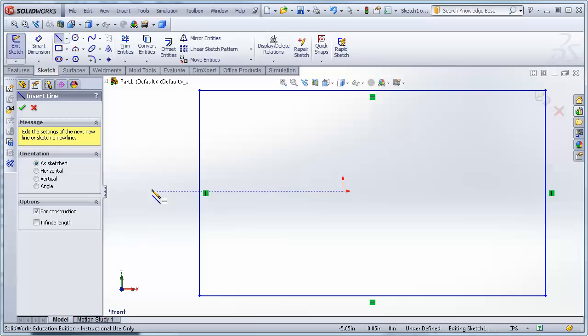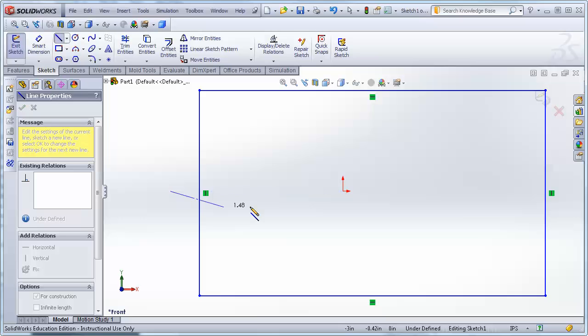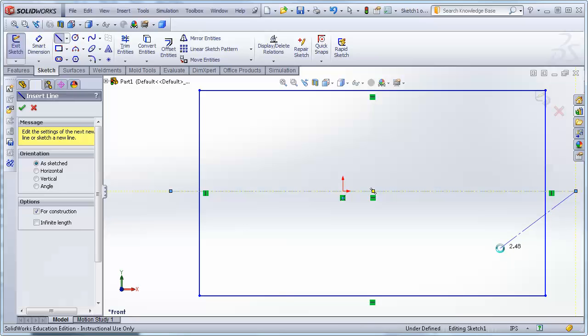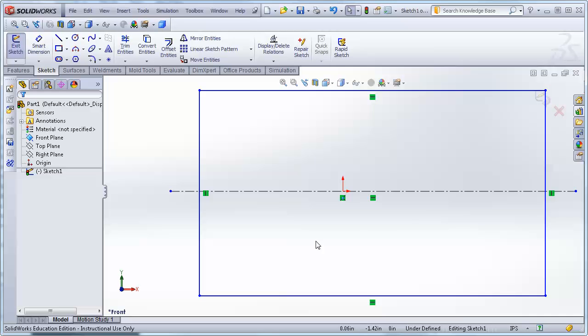And so I'm going to create a center line that extends from the left of the rectangle and is snapping to be level with the center of the coordinate system. I'm going to force this line to snap level and hit escape. Now notice I get a couple of marks on this thing. This mark says this line is horizontal. This mark says that this point and that line are coincident. My rectangle, because I did a horizontal rectangle, said that line's horizontal, that line is vertical.